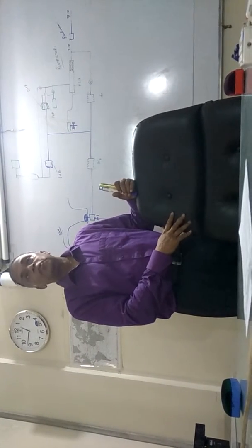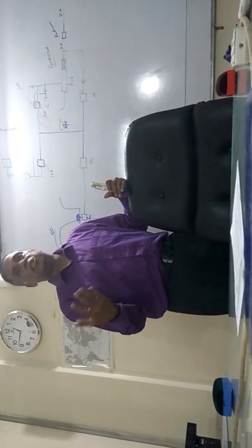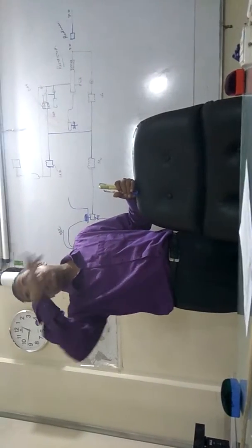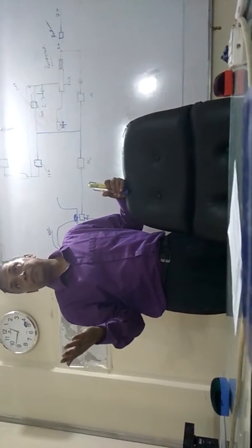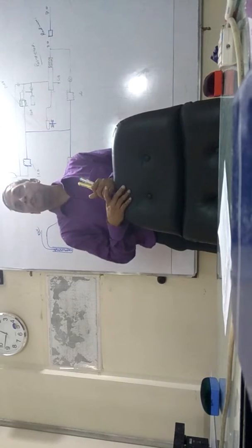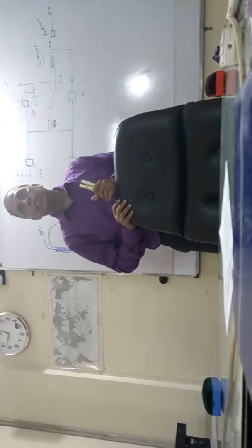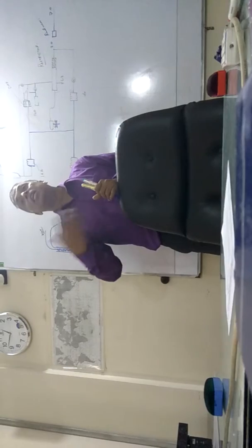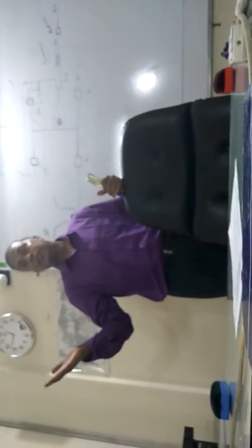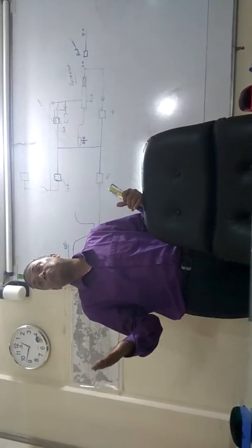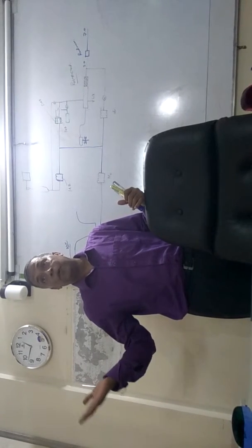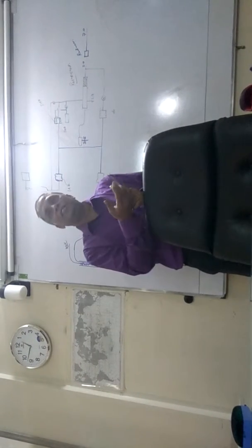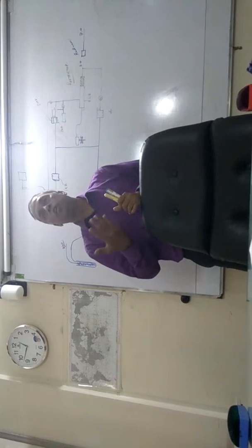Right. So since we are talking about temperature, that controller will have a scale of temperature. For a jacket cooling water system, possibly it will be 0 to 100 degrees C. For steam or other high temperatures, it can be higher. For example, exhaust gas temperature can be graduated to 500 or 600 degrees C. So it depends on the system and what we actually want to achieve there.